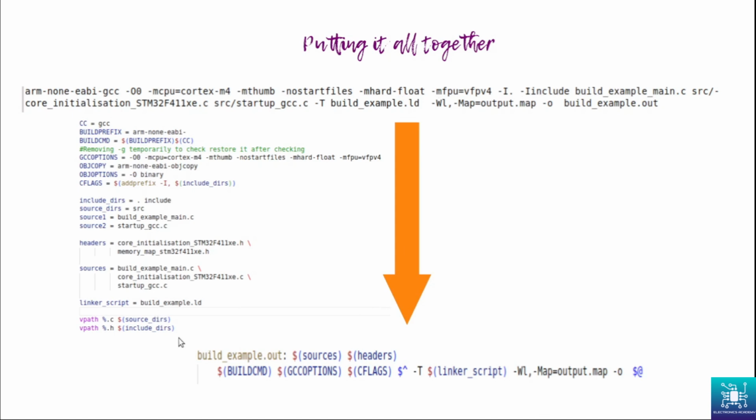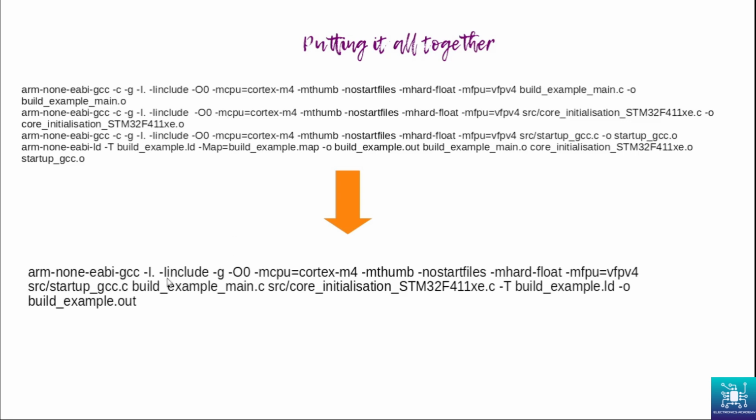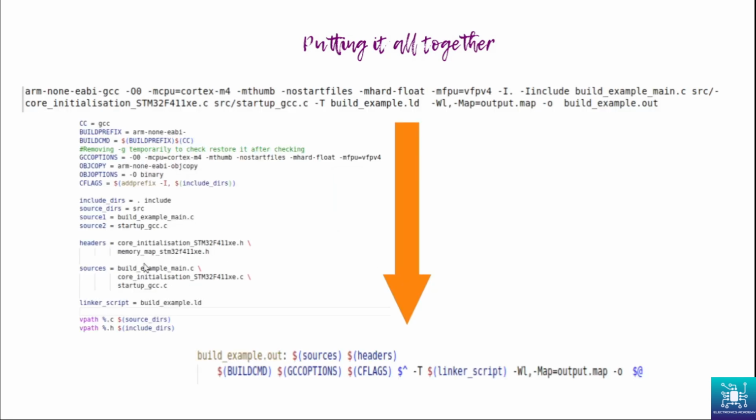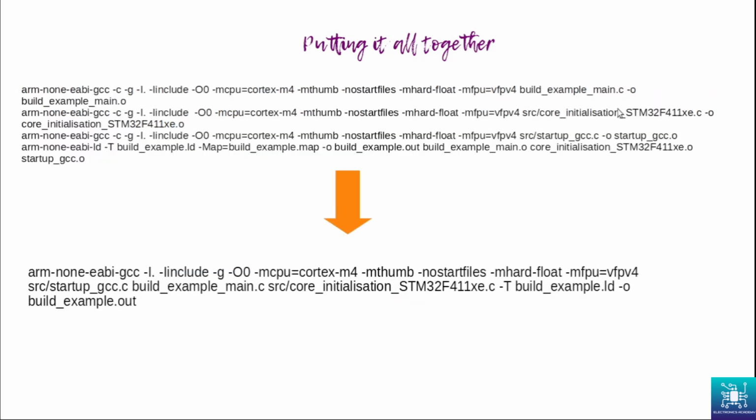Okay. So how does that happen? Let us go through this here, and we will of course see it separately in the makefile also when we see the demo. But then this is the command that we saw previously, the combined command that we have been using. Only 2 things have been added here. That is the -Wl,-Map=output.map and build/example.out, which we did not put here.